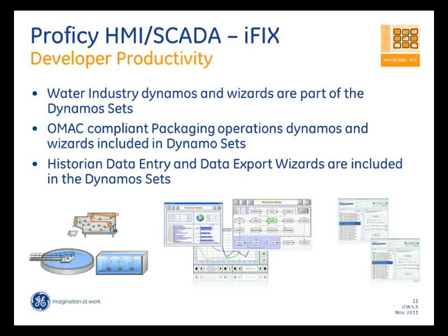You would have the OMAC compliant Dynamo sets there, so you have the OMAC state model. You have certain pre-built screens that get installed as well, which are geared towards a packaging operation with a chart object, and these screens were pre-canned to accept OMAC compliant registers from different PLCs. So if you use a PLC that has a configuration as per the PackML standard, you can tie it into these graphics, and these graphics have been pre-canned from an animation perspective to accept PackML states and animate themselves. So that's already part of iFix 5.5. It's a default part of it.